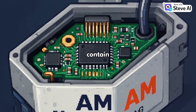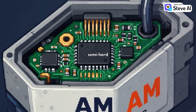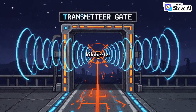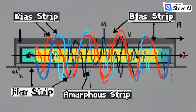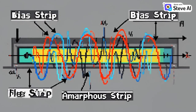AM tags contain two internal strips, a magnetostrictive amorphous metal strip and a semihard magnetic bias strip. The transmitter gate emits short, alternating magnetic pulses at 58 kHz. The bias strip provides a steady DC magnetic field that tunes the amorphous strip to its perfect elastic operating point, causing it to mechanically expand and contract at high speeds when exposed to the transmitter's pulses.